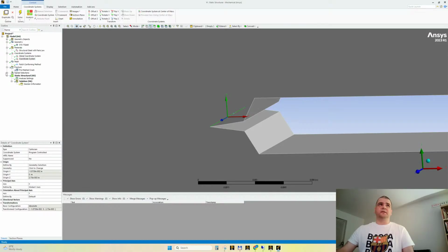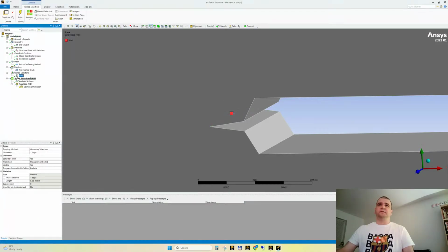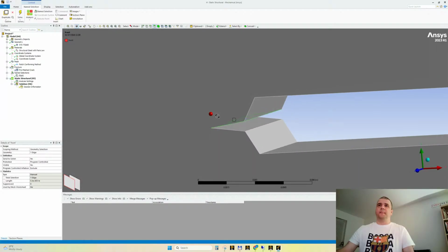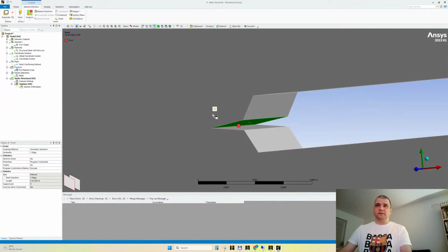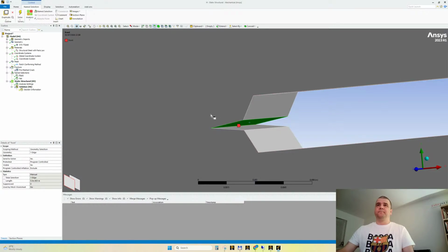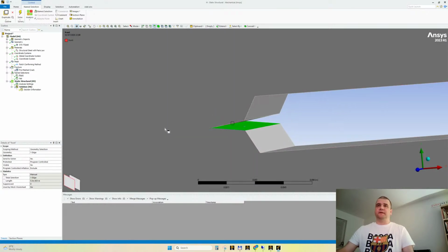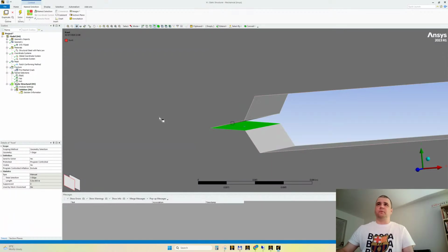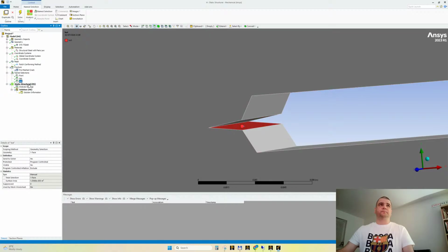And it created here this named selection. This is the front. We changed the geometry filter to face. N, create named selection, N, top. We repeat, click this face, N, create named selection, and I abbreviated to bot from bottom. This is what we need: front, top, bottom.